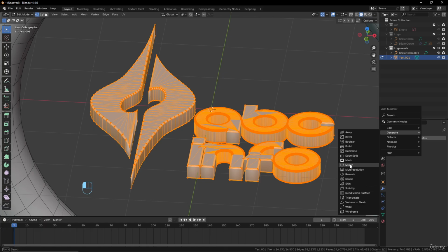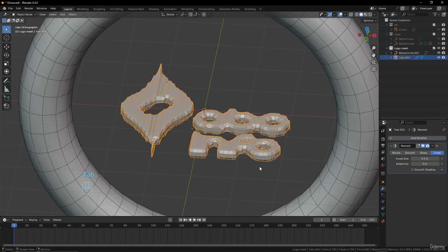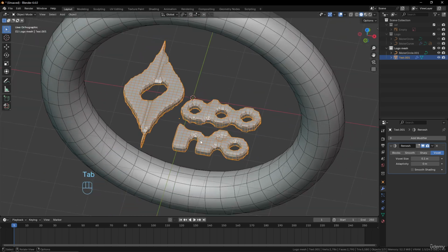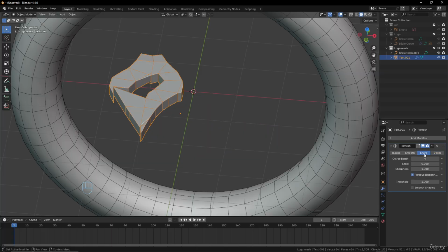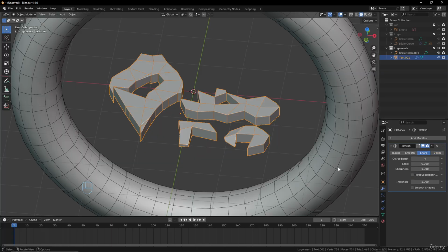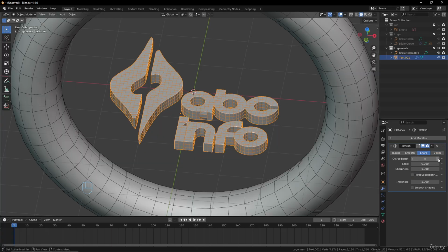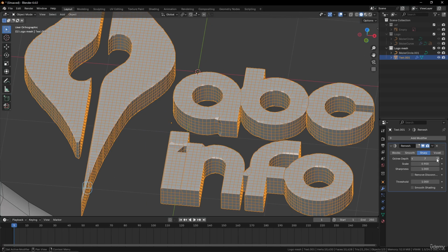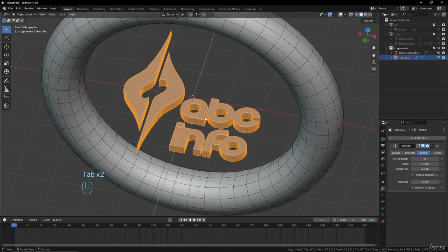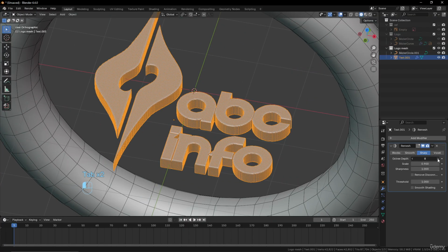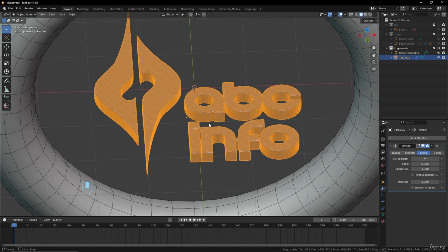The remesh here. Good. And now we'll have a kind of shape like this. Oh, it doesn't work well in the beginning. But we can use the sharp option, remove disconnected here, and increase the depth a little here until we have a nice shape. And see what we have. We have a lot of quads now. So it will work better for deformation, okay?